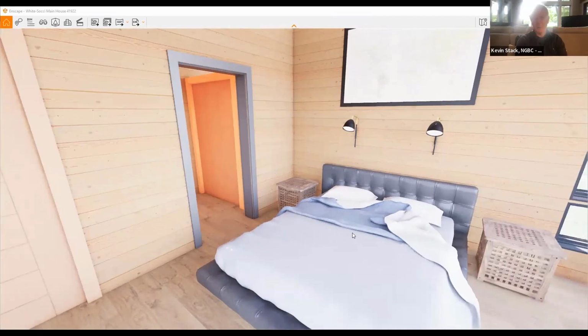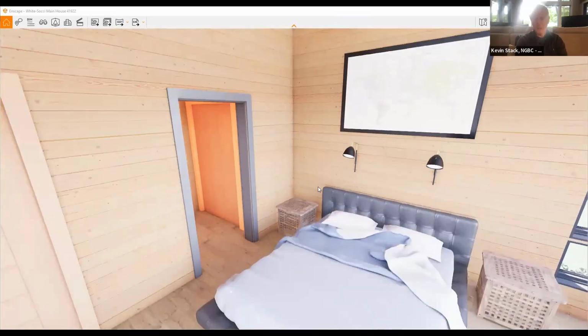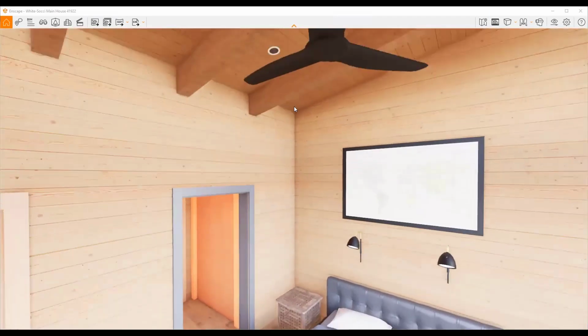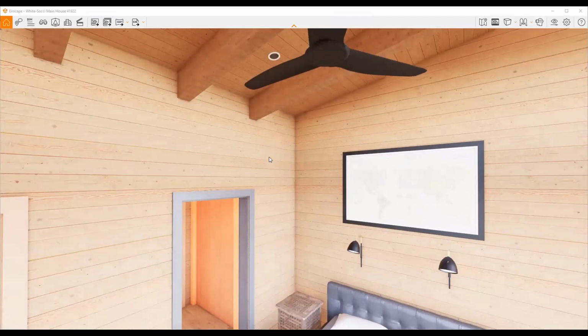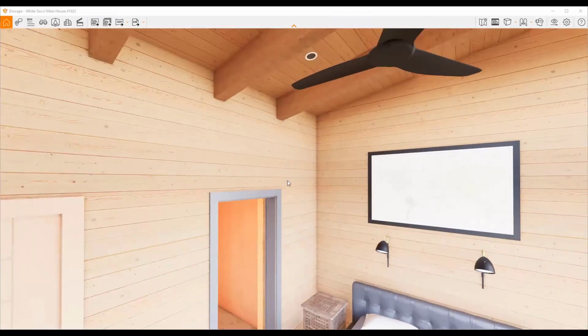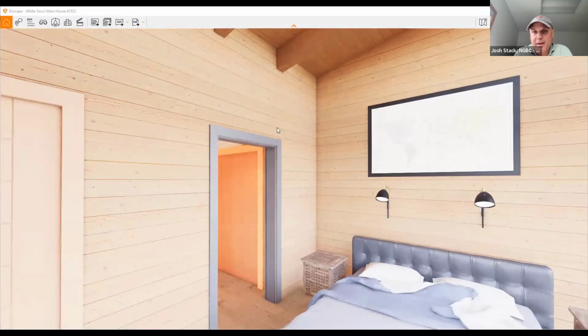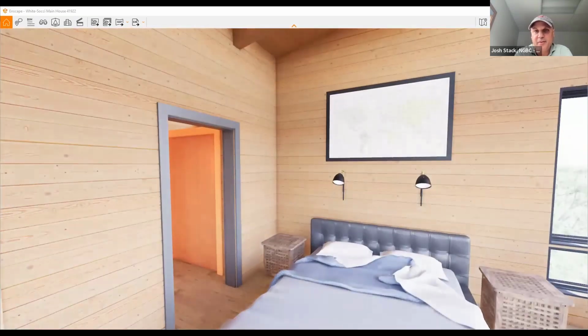Can we get up into the wall space and throw heat from above on that space somehow, if we framed it properly? I'd prefer that wall out because that's the three-sided shear wall behind the bed, right? So if we brought that wall forward enough to get ductwork into it, we'd lose space inside of the room, but it'd be one way to maintain continuity of the ductwork distribution from the basement level if we hit that and went up.